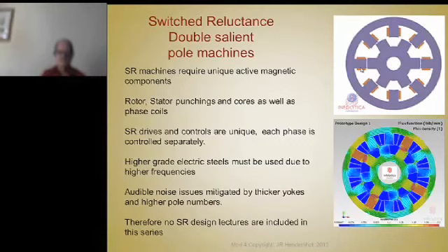These switch reluctance machines have a very simple structure. The rotor can be punched out of the stator in a progressive die, and the stator looks like an internal gear and the rotor looks like an external gear. Simple as that. There are combinations of stator and rotor teeth that will work with 2, 3, 4, 5, 6 phase machines, and outside of those they won't work.